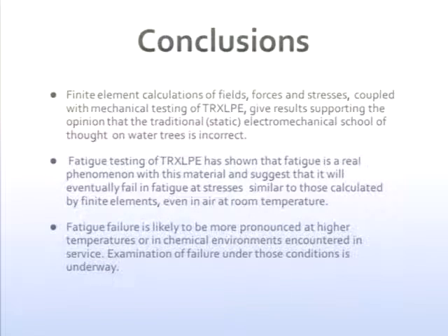And fatigue testing has shown that fatigue is a real phenomenon with this material and suggests that it will eventually fail, years, tens of years, in fatigue at stresses similar to those calculated by the finite elements. Even in air at room temperature, fatigue failure is likely to be more pronounced at higher temperature or in chemical environments encountered in service. An examination of failure under these conditions is underway.